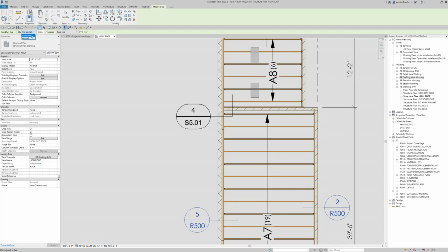You can have horizontal or vertical, a leader, or not have a leader. We want a leader. And then you have attached end, which would be a straight leader from the symbols to the object, or free end, which you can add a shoulder to. So we'll set that. And once you hover over, it will change to match symbology for different items.